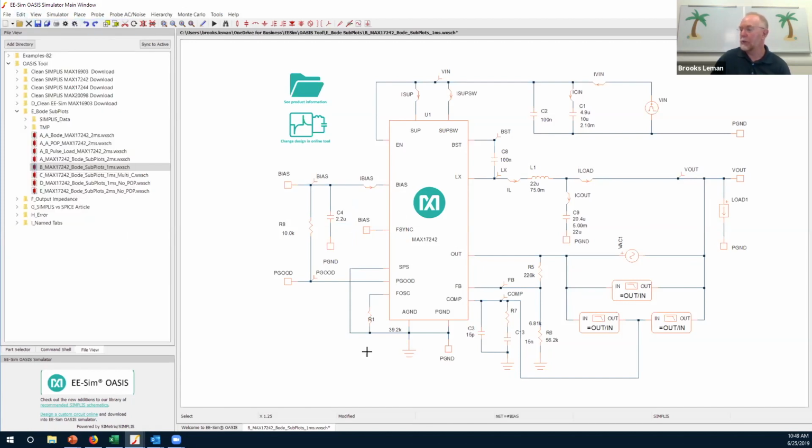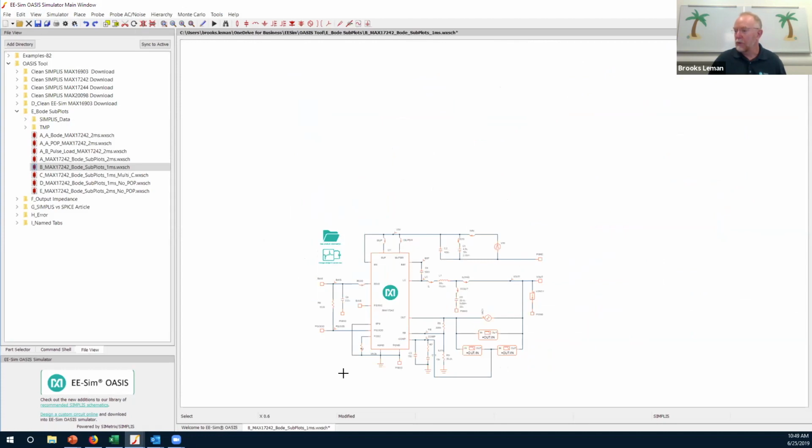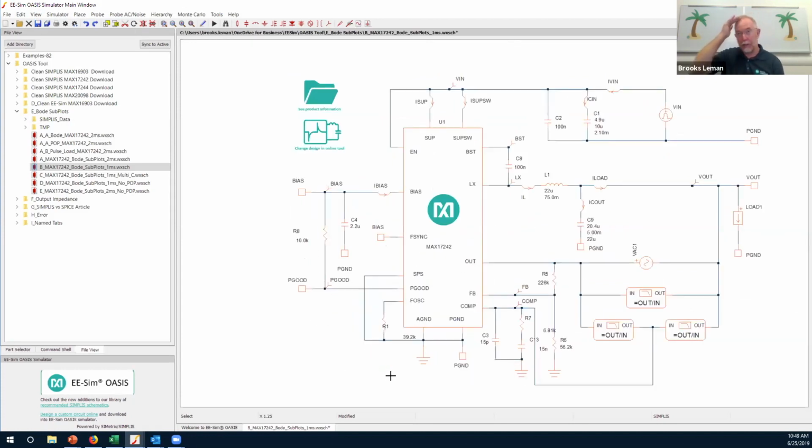When you're wiring the schematic, we try to avoid doing this. That's what we call a dot cross, okay? And one of the reasons is it may not be clear if those are connected if you zoom too far or look at the schematic on a device that has a really small screen. So what we try to do is fix that by using only T intersections.